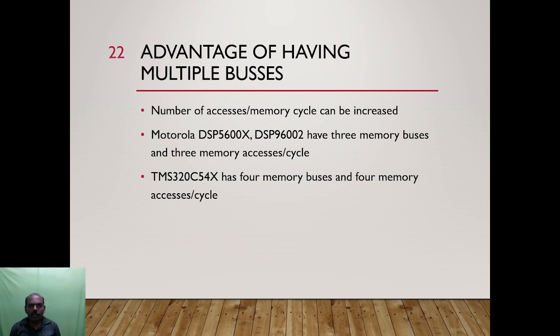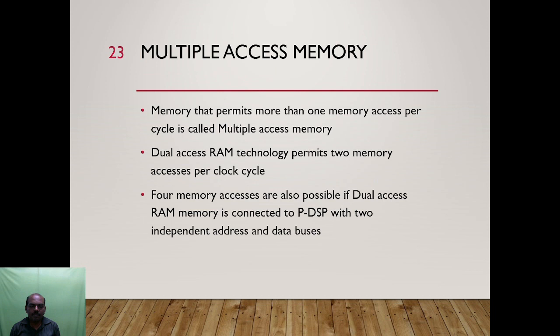Advantages of having multiple buses: the number of memory access cycles can be increased. Motorola DSP 5600X series and DSP 96002 have 3 memory buses and 3 memory access cycles. TMS320C54 series have 4 memory buses and 4 memory access cycles.